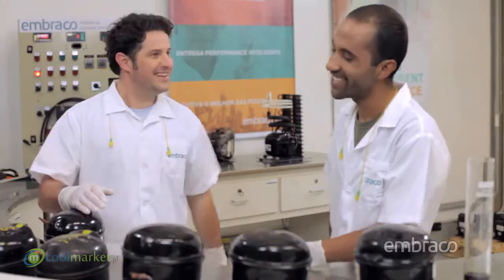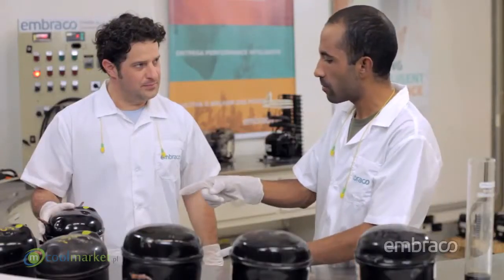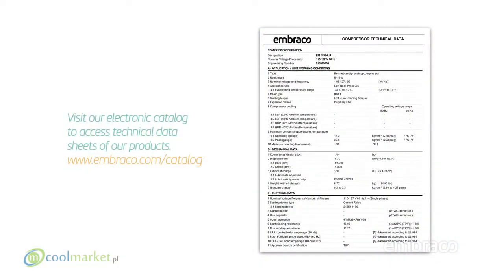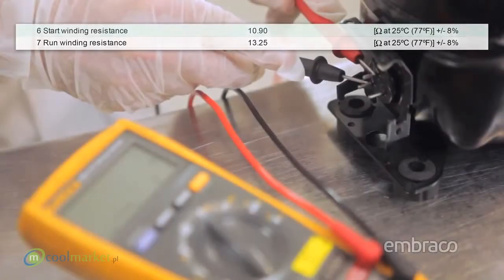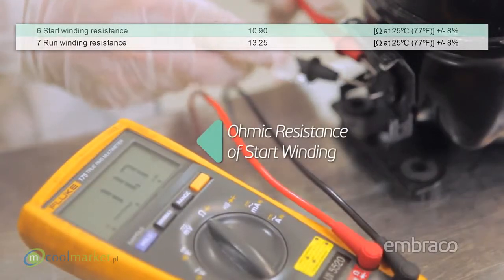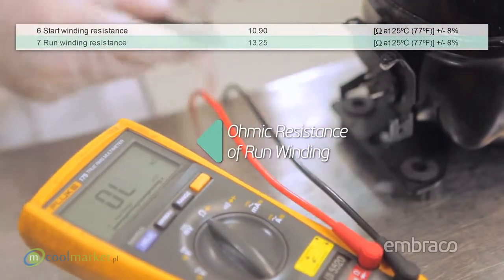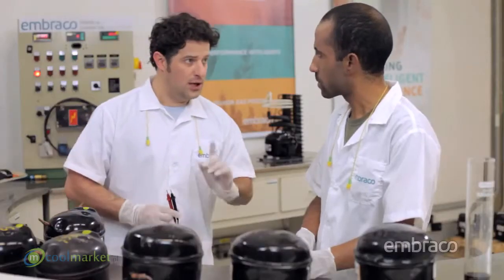Remember the video about changing compressors, right? Oh, right. So how do we check if the compressor isn't defective? First, we check the ohmic resistance of the windings and compare it with the information on the datasheet. Now let's turn on the compressor and check for noise and compression.